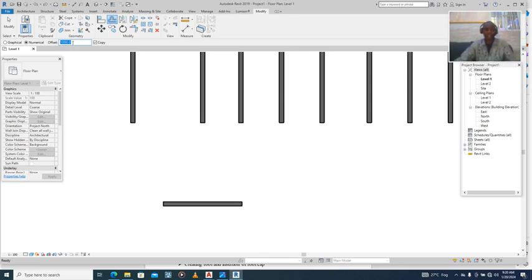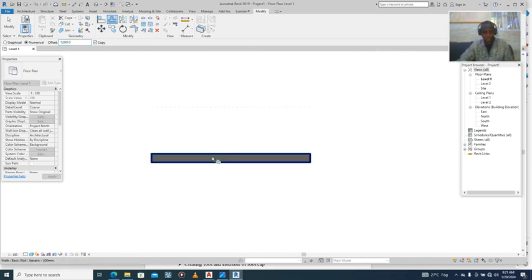Maybe I want to offset this wall to a distance of maybe 1200. I'll press 1200, but I want to show us something when it comes to Revit offset. I've already pressed 1200. Make sure I'm placing my cursor at the front of any digit I want to input. Once you come to this wall, you can either offset in this direction or offset downwards.